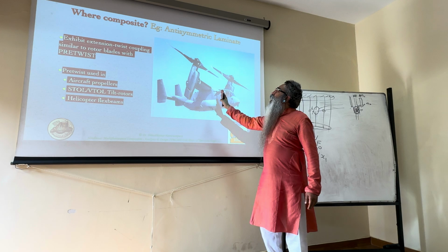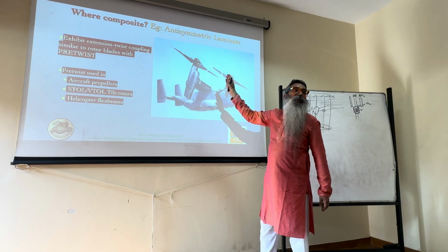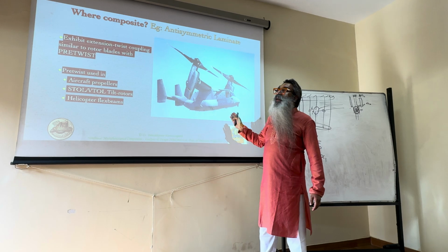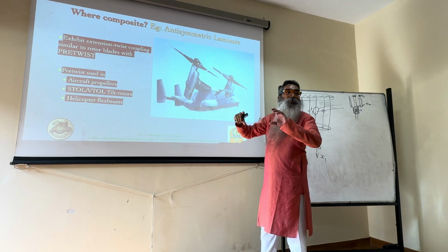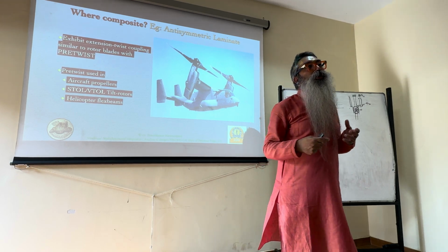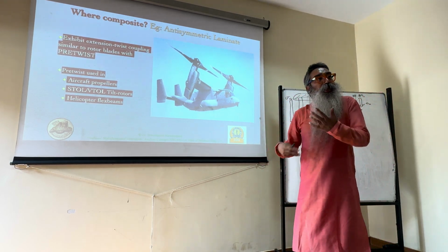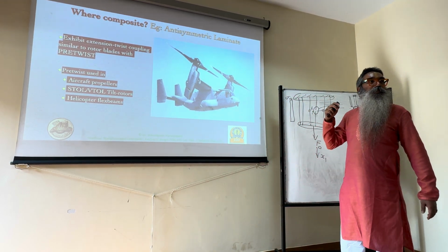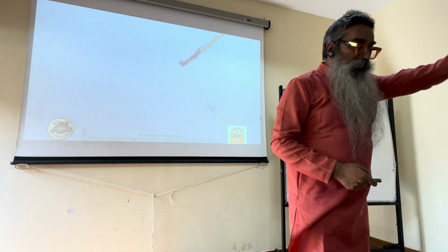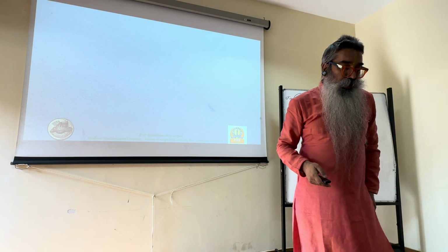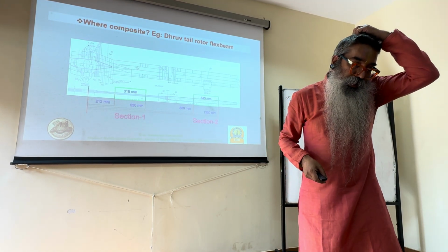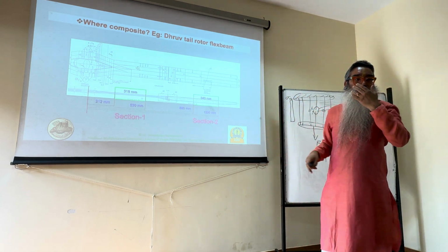And you would see that if it's for vertical flight or hover, the kind of requirements on the blade is very different from the forward flight, and you can make those differences by changing the twist angle through the pilot controls. And you can bring in some of those couplings a priori by manufacturing with a certain pre-twist and with certain anti-symmetric laminates.